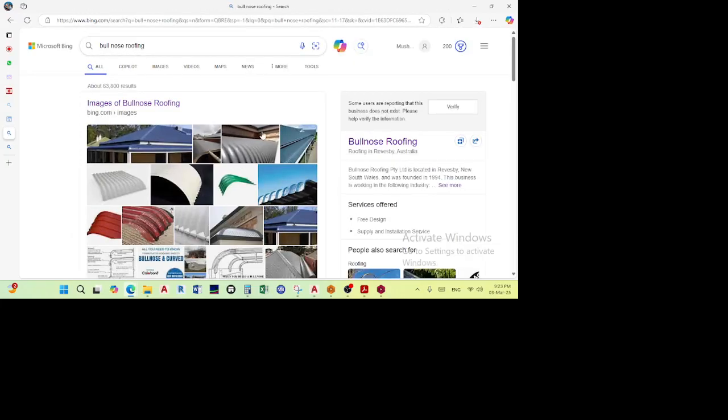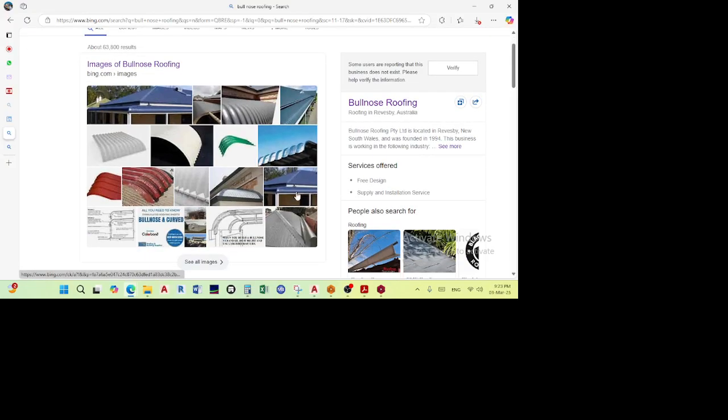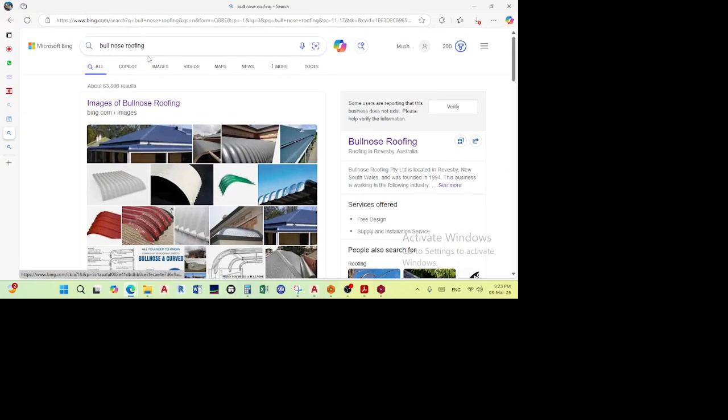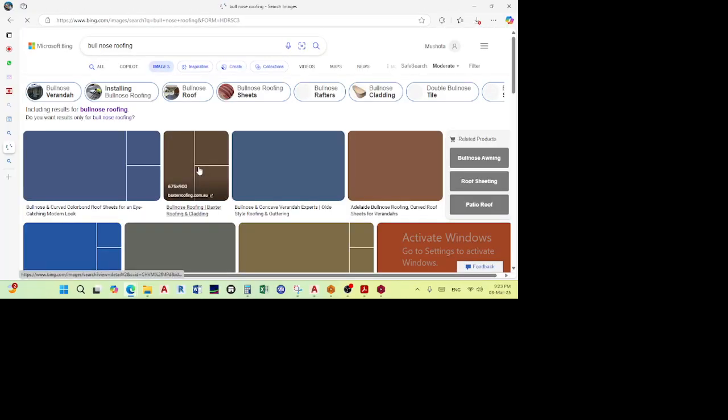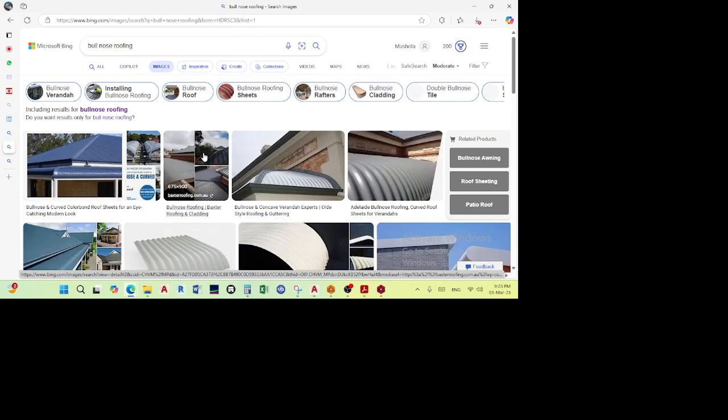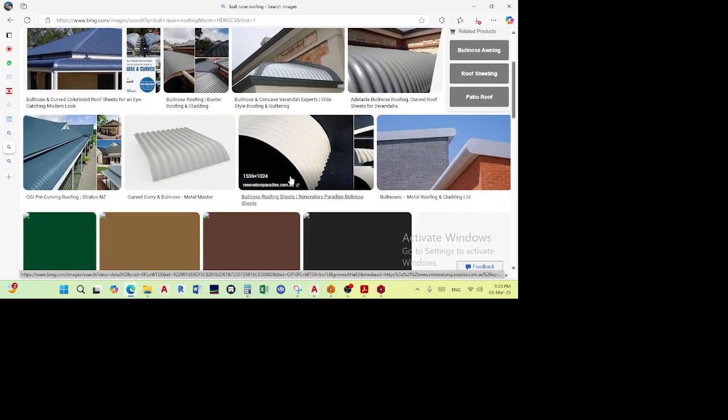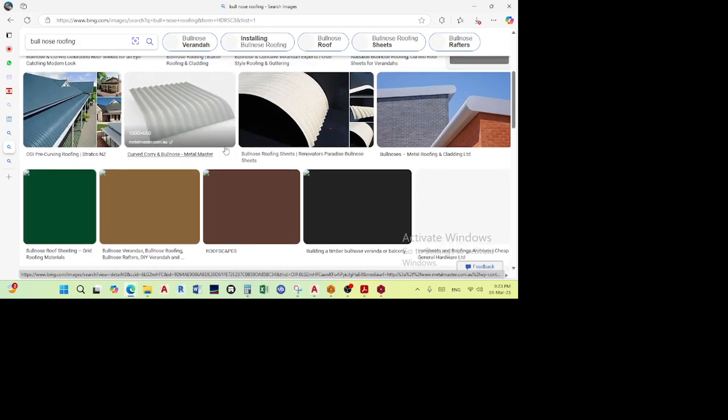Like a cladding, a side cladding here. You see? Yeah, so you can keep that. And then you put some purlins on the side so that you can have somewhere to anchor those nails. Something like this. Like that.